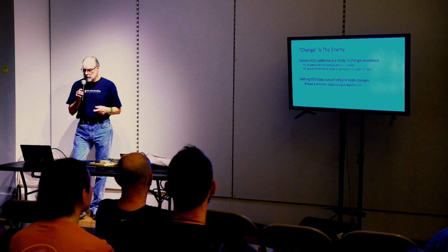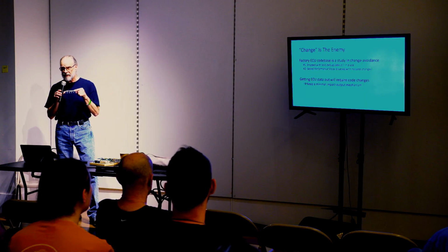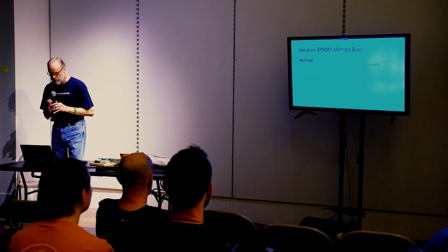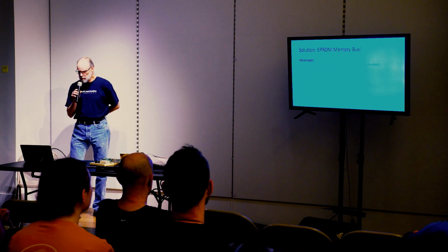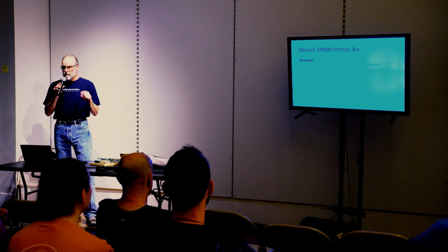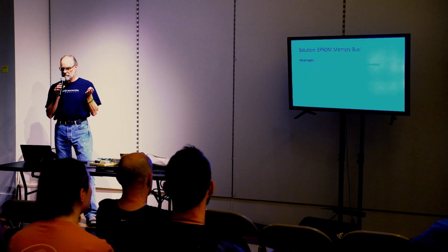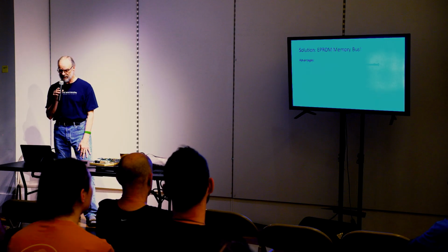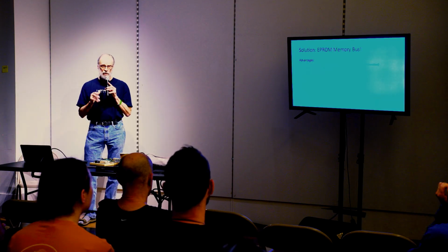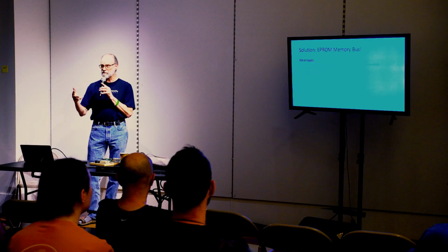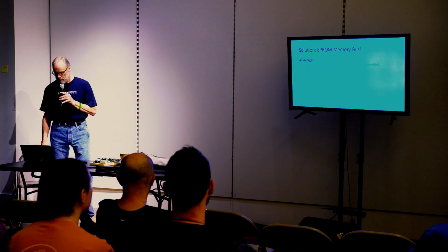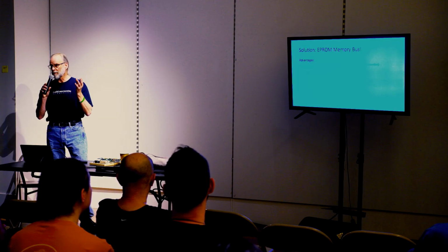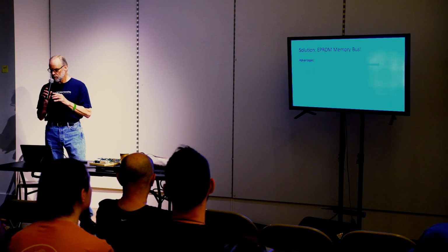So from my point of view, getting the data that I wanted to get out, I needed to do it in a way that had minimal impact. So my solution was to use the EPROM memory bus. It has minimal timing impact, so I can get 23 bits of data out in 2 microseconds, which is absolutely as fast as that processor can do anything. It's mechanically accessible, meaning the EPROM's in a socket, so I don't have to be doing weird stuff to their circuit board. And it's electrically simple. It's not like I'm trying to interface to USB 4 or something like that. It's just a really simple protocol.